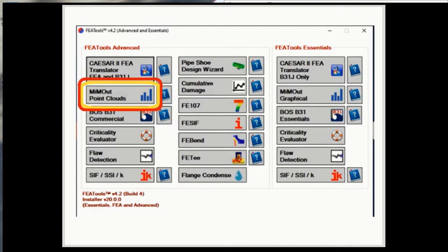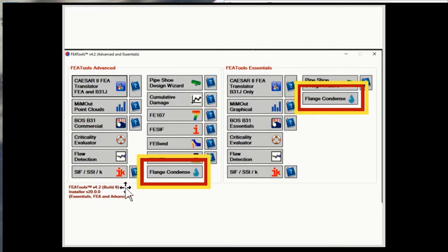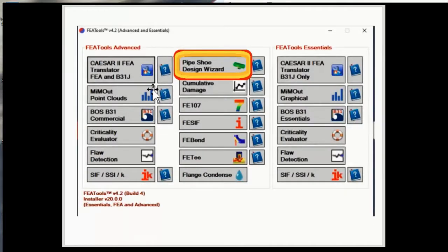These buttons let you quickly check flange locations using simple rules of thumb to see if problem areas appear due to bolt-up tolerances or operating overloading. If you have locations where you think you might have problems, then the exact loads that are developed can be used to further evaluate the flange. This is what we're going to look at first.